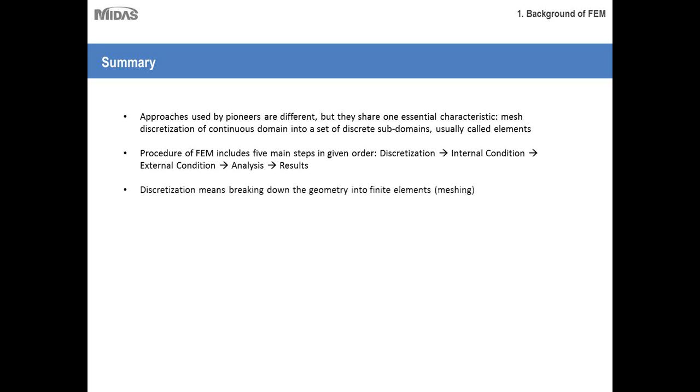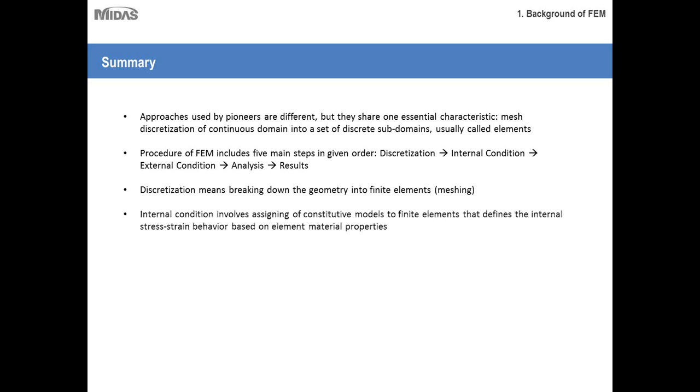Discretization means breaking down the geometry into finite elements. It's also known as meshing in our day-to-day language. Internal condition involves assigning of constitutive models to finite elements that define the internal stress strain behavior based on element material properties. So how these stresses will propagate, how the deformation would occur under different types of loads, when the material will yield is something internal to the structure, and that could be controlled by constitutive models.